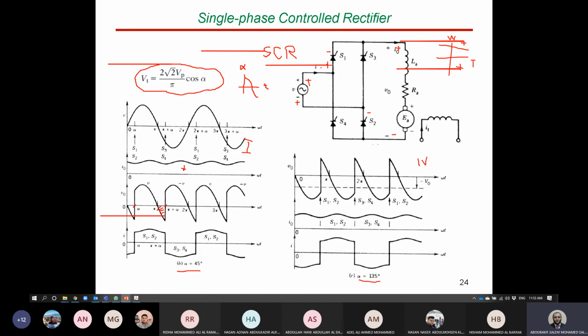The seen impedance value will be a function of the thyristor firing angles. However, during all of the operation, the supply can still see an inductive load, because the energy can be returned to the supply as we discussed.